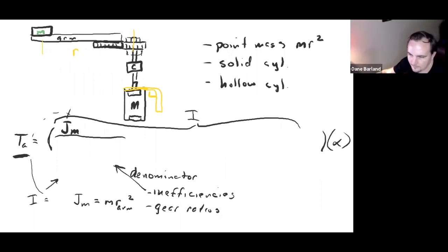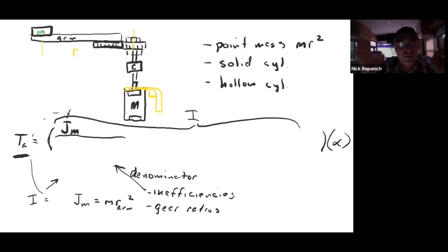As goofy as it sounds, the easiest thing for me to do is visualize me running around on the machine. So now I'm going to start here, and I'm going to run along the machine. And I have to look for two things. Any place there is a discontinuity in velocity, meaning I'm jumping from one thing, kind of like getting on an escalator. When you come up to an escalator and the floor's not moving, but the escalator is, there's a discontinuity there, and you have to jump at it to make it move. There is an inefficiency. Guaranteed.